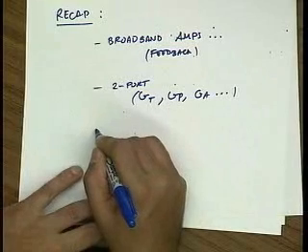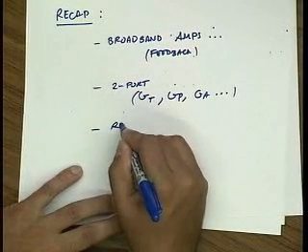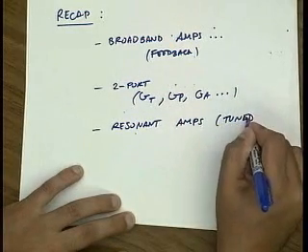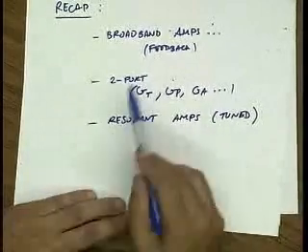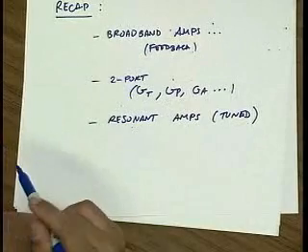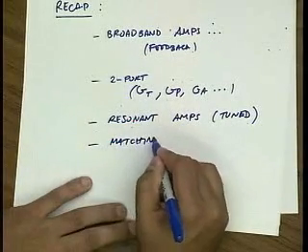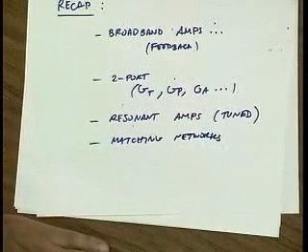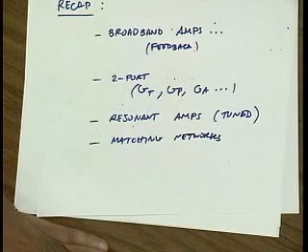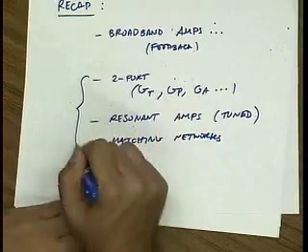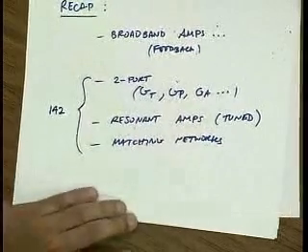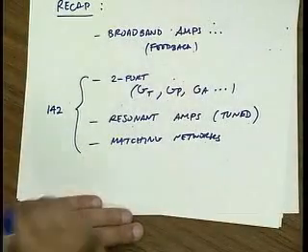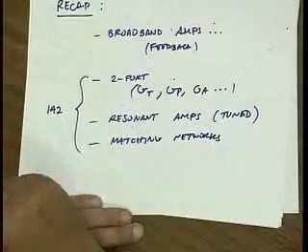And then that really led us to two different concepts. One was resonant circuits. Resonant amps are actually usually called tuned amplifiers, where we used resonant elements to tune out the capacitances in the circuit, and also matching networks, which let us transform the source and load impedance to a more optimal value to try to maximize the power gain. So you can see that this is really stuff we've learned in 142, because we're looking at the limits of performance. What's the best power gain we can get out of a transistor? What if I put feedback around it? What if I use matching networks?